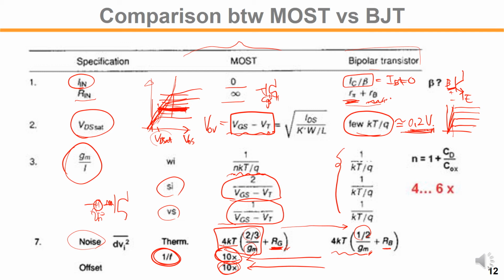It can operate as a digital switch better than the BJT, because the BJT requires non-zero current onto the base. This prevents us from using the BJT as a switch, because some current flows, requiring some current for logic operation.